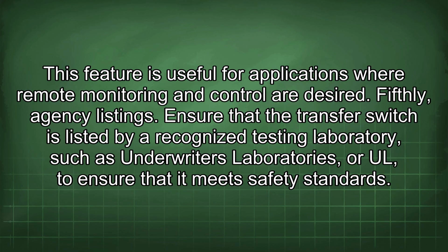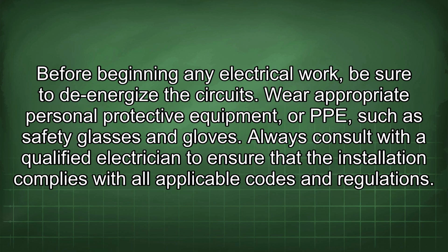Fifthly, agency listings. Ensure that the transfer switch is listed by a recognized testing laboratory, such as Underwriters Laboratories, or UL, to ensure that it meets safety standards. Before beginning any electrical work, be sure to de-energize the circuits. Wear appropriate personal protective equipment, or PPE, such as safety glasses and gloves. Always consult with a qualified electrician to ensure that the installation complies with all applicable codes and regulations.